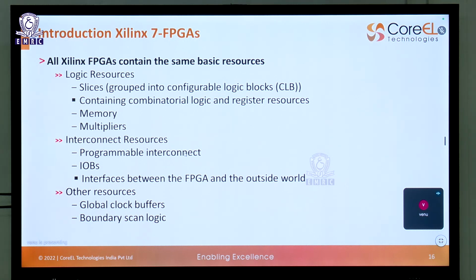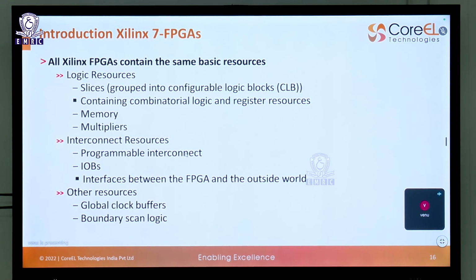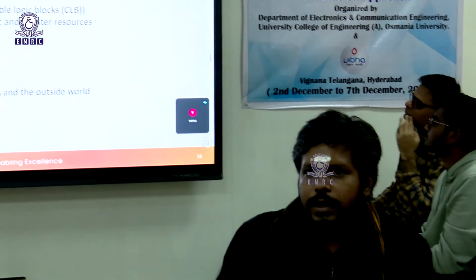But when we go higher, when we go to UltraScale Plus architecture, there we won't be able to see slice L and slice M. Okay, there are no different slices for logic and memory. There is only one slice. The advantage there is, here in a CLB, we are looking at 4 different blocks of LUT, right? In 7 series, we'll be looking at 4 blocks of LUTs.